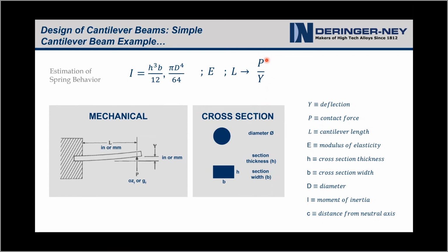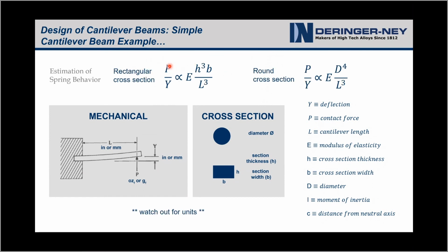Very frequently, when you go to do calculations, this is represented as either, hey, calculate the force or calculate the deflection from the other spring attributes. But really, we're designing a spring. And the spring rate is critical because we know that sometimes the deflections can be variable. Either that's designed in or that's a stack-up of tolerance.